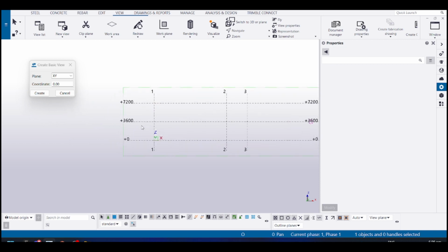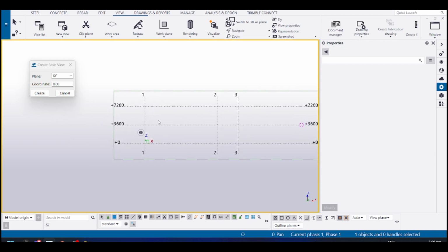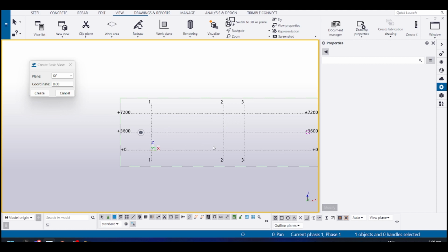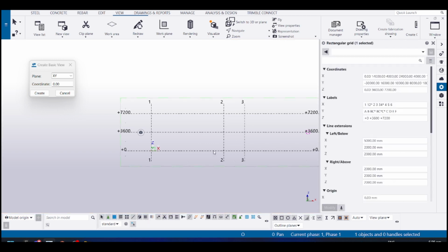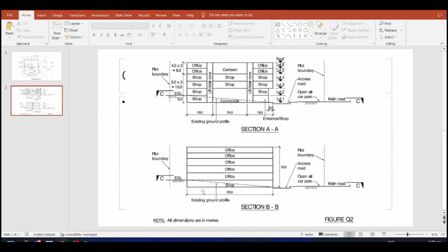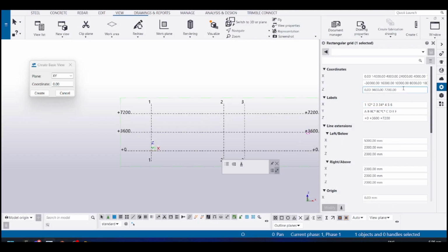I have these elevations set in my model in the grid system. So I can again modify these things now. Let's select this button, and this time I'm not going to do any direct modification. It's a fairly straightforward thing now. I can put in a 0, then 3 by 5, and then 4 by 2. So I just go here, 0, 3 star 5000, and then 2 star 5000.